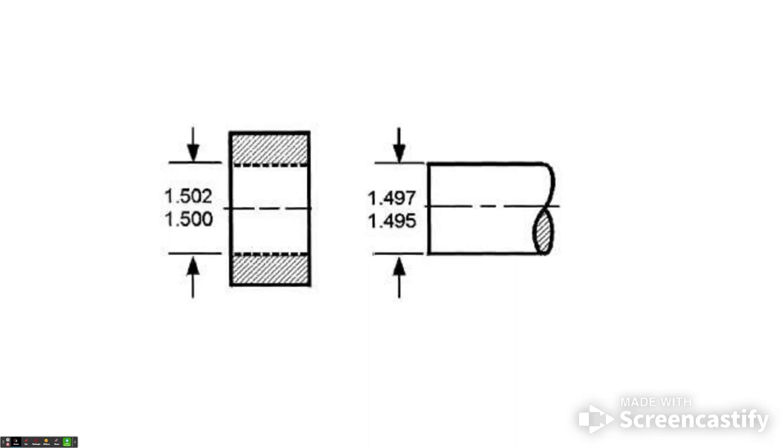And we've already talked a few times in the classes about a clearance fit, a slip fit, or a press fit, what I usually refer to as a clearance, slip, or press. Some of the other industry jargon you'll hear will refer to these as interference fits as well. So be aware that there's some differences in terminology there. And of course, wherever you're working, you'll get used to that terminology.